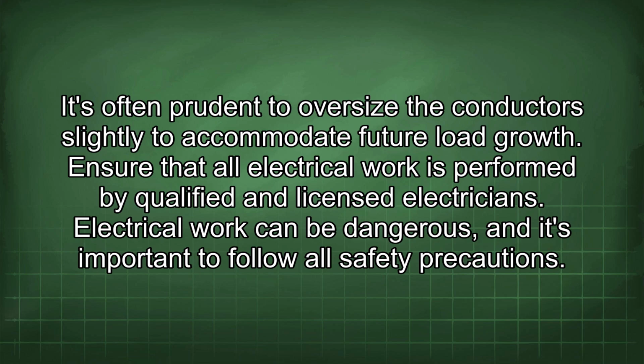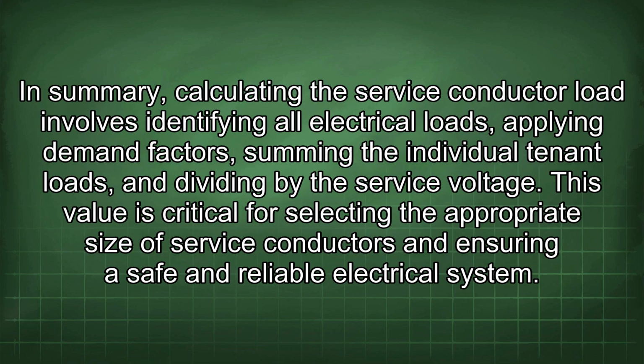Ensure that all electrical work is performed by qualified and licensed electricians. Electrical work can be dangerous, and it's important to follow all safety precautions. In summary, calculating the service conductor load involves identifying all electrical loads, applying demand factors, summing the individual tenant loads, and dividing by the service voltage. This value is critical for selecting the appropriate size of service conductors and ensuring a safe and reliable electrical system.